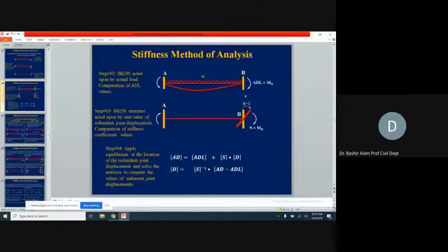That displacement was in the opposite direction to whatever was produced by the actual load. And we added up these two displacements to get the effect of the original structure and satisfy the compatibility condition. Here, in terms of the actions, we are satisfying the equilibrium condition.